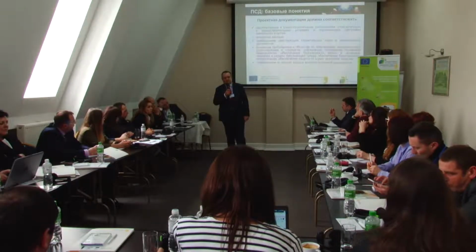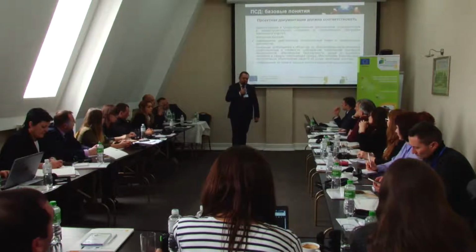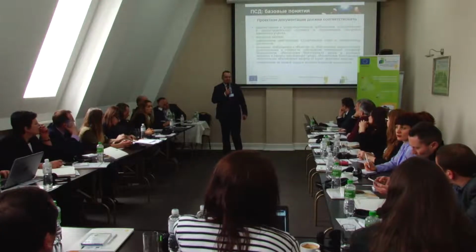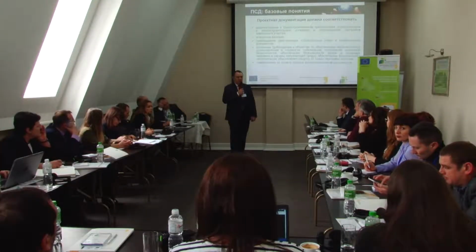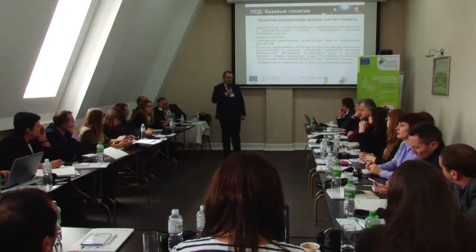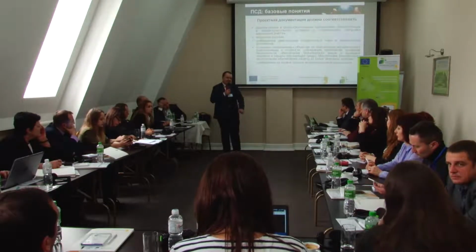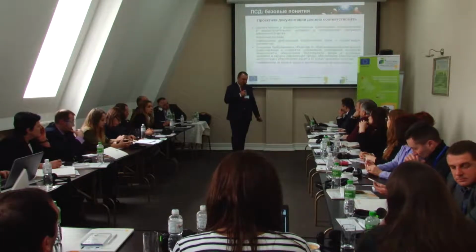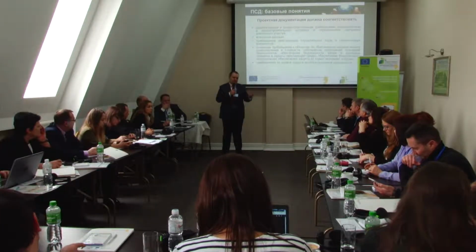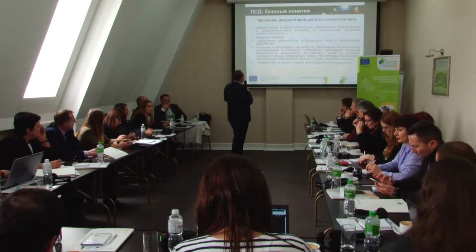And if we speak about, let's say, facilities which are located in a historically valuable area or within the heritage, UNESCO heritage, or some other heritage laws, the designer should take this into account while preparing the technical design, because it may so happen that this building cannot be thermally refurbished because changes in the facade of the building are not allowed by certain cultural or other restrictions.